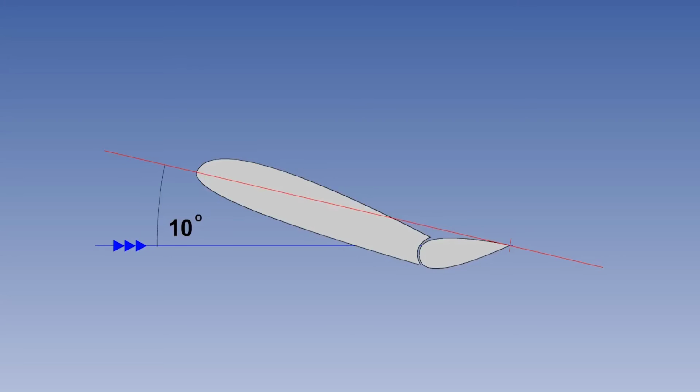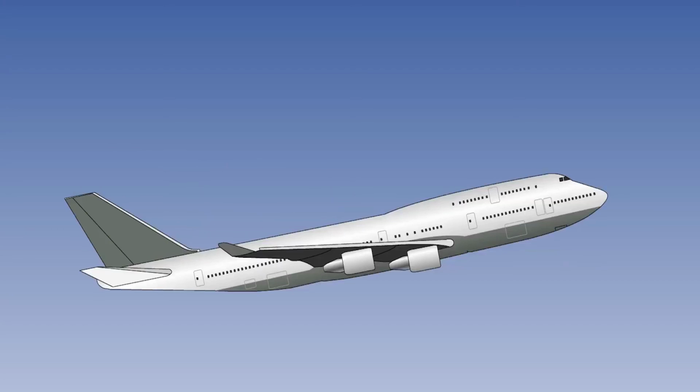The moral of this is that ailerons should be used with great caution when close to the stall. Swept-wing aircraft basic stalling requirements, however, are designed to enable safe use of the ailerons as far as stall recognition, with small amounts of rudder, if smoothly applied, to coordinate with the ailerons. Various means of achieving this capability are discussed later.